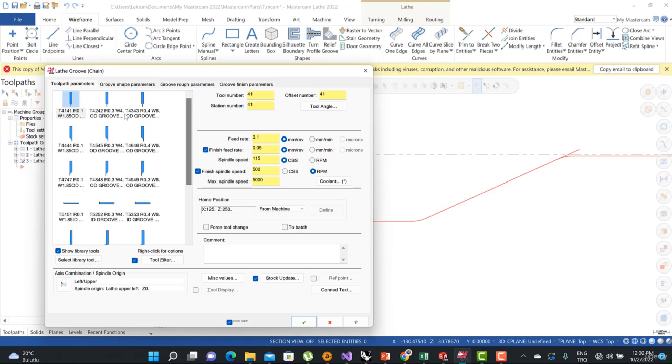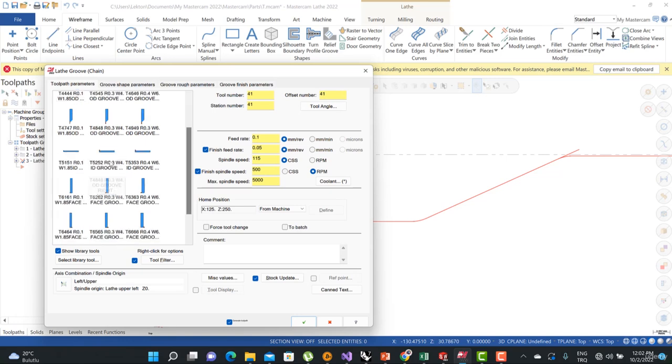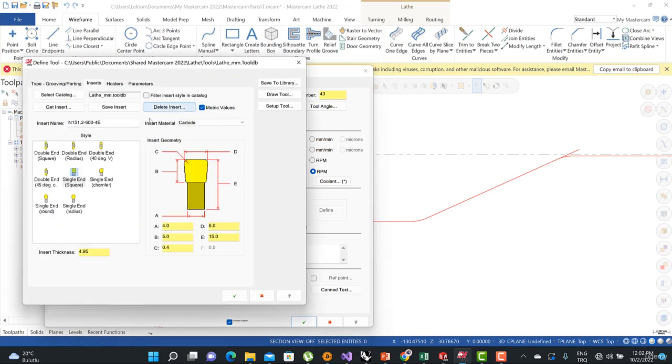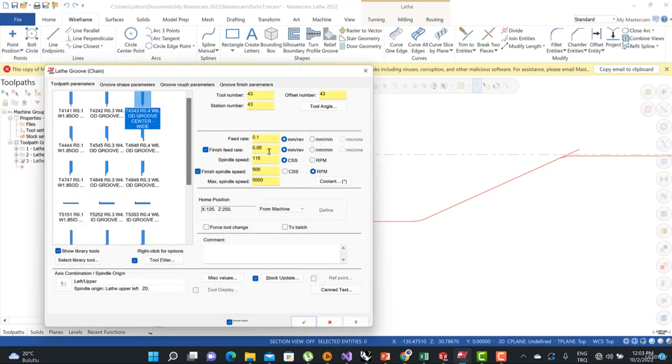Okay. And this is tool, and I can select. For example, I prefer to use that one. The distance is important. This is the 6 mm, and the radius is also quite important. So I can select my feed rate, and I prefer to use constant cutting speed.